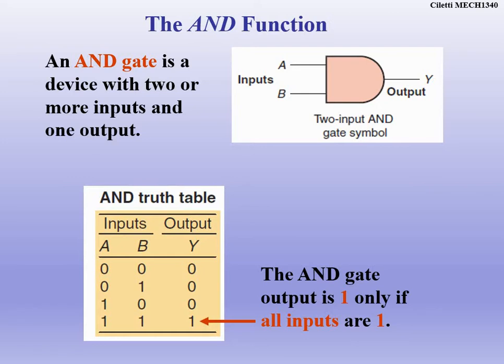So we use a truth table here, and that's kind of what I just read through. A truth table tells us all of our possible input combinations and what that output will be. So when we are ANDing, the only true output will be when we have a 1 and a 1. We will get an output of a 1. For all the others, our output will be false. For 0, 0, 0, 1, and 1, 0, our output's false or 0. When we have 1 and 1, that's the only time we get a true output, which is a 1. So this is an AND gate, all right?